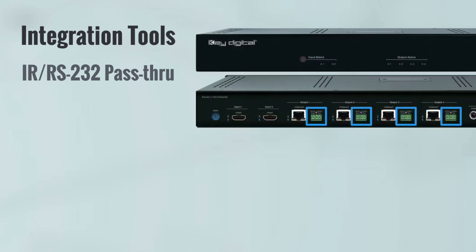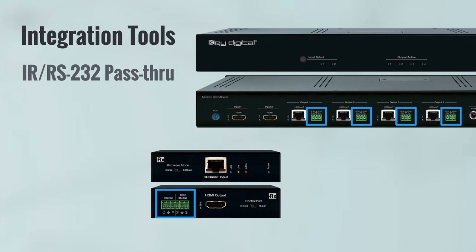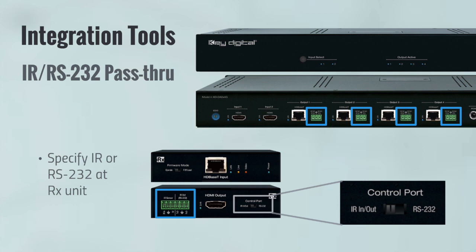Here is a closer look at the 3-pin Phoenix connectors that you'll use on the 2x4 2x8G and on the connections used at the RX units. Now, it is very important to note that you must specify IR or RS-232 usage at each and every receive unit. The default setting is IR.